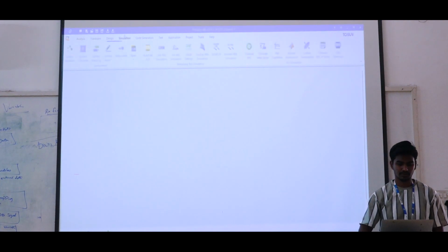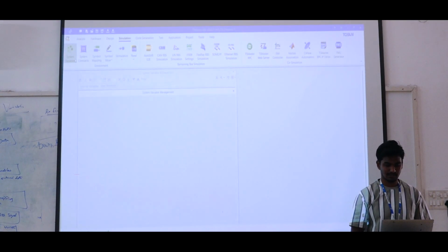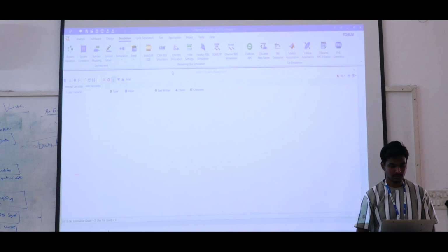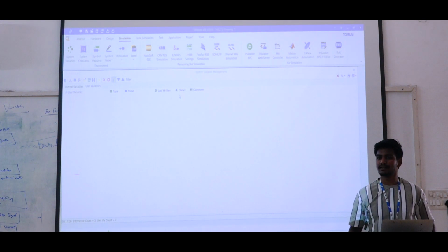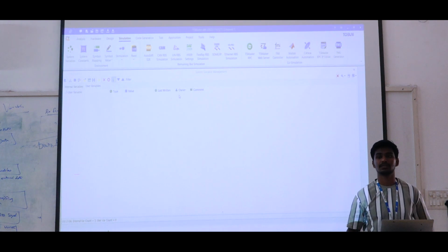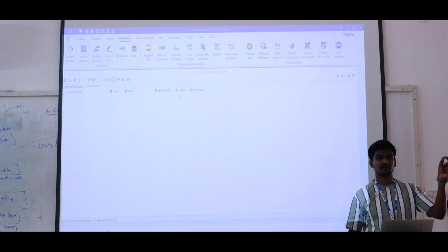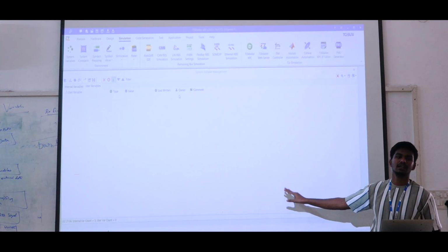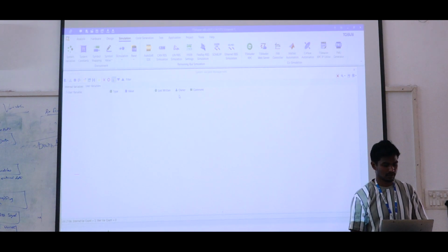Go to simulation. So system variables is there. Just open the system variables. The window will look like user variable, type of values, last return, owner, comment, these kinds of things. The system variable really gives a feel like a signal. What we created from a CAN database signal, like the definition of signal name, length in bits, like that we created. Instead of that, we don't have any length in bits; we set the minimum value, maximum value, whatever we require, and create this.